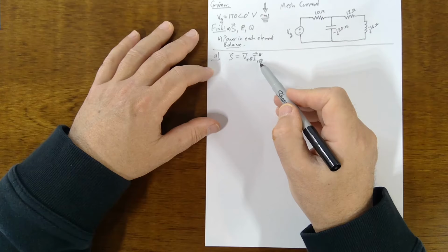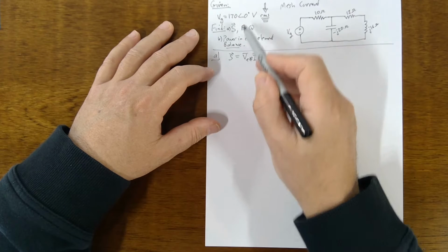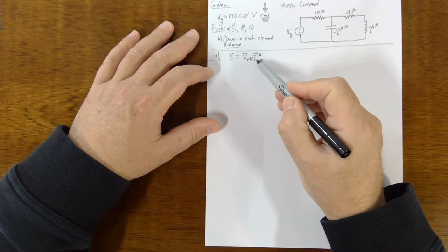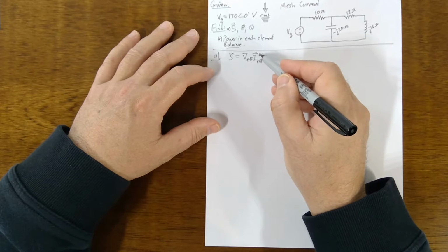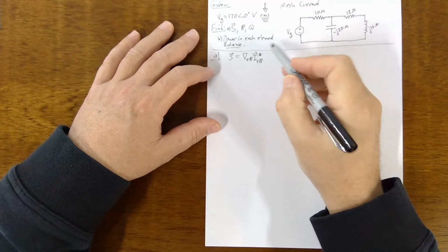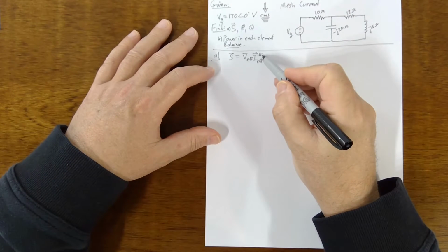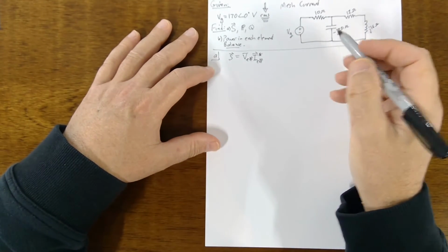So if we had I RMS, we could take the conjugate and get S, and then we could peel that apart and get P and Q out of that. This conjugate thing, it's sort of lost in the math why that's a conjugate, but you could go through all the derivations in the text if you felt like it, but I prefer to take that on faith and just use it as a tool.